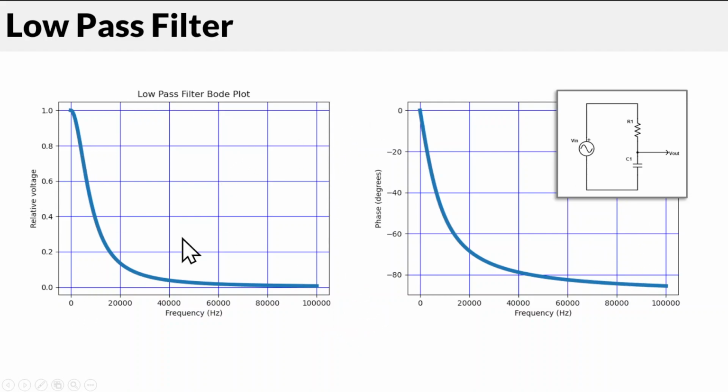Now, this isn't the normal way we would plot these, because there are considerable changes in the way these graphs are drawn. We have those reciprocals there with lots of 1 over frequency, 1 over RC and arctangents, etc. Those values change quite quickly for small changes in frequency, particularly close to the lower end. And so these graphs often don't really show all the detail of what's happening. So we tend to prefer to plot these graphs using logarithmic scales and using a unit called the decibel.